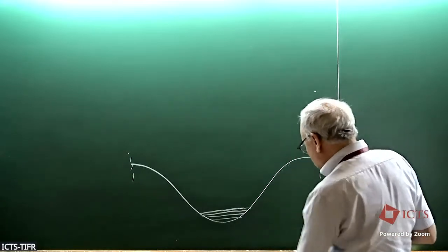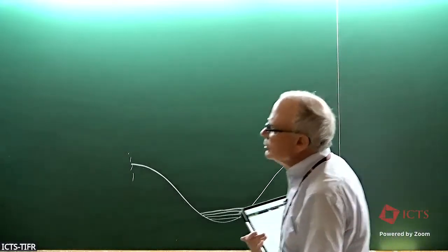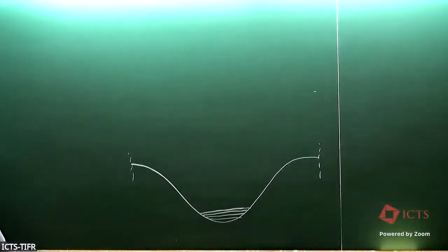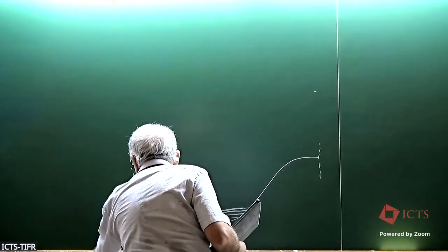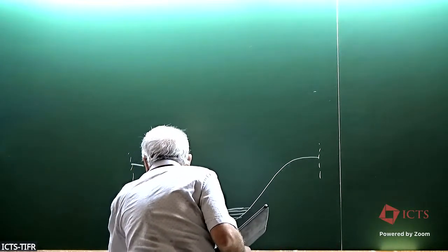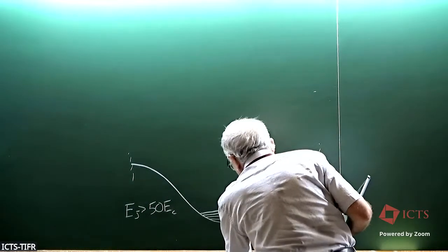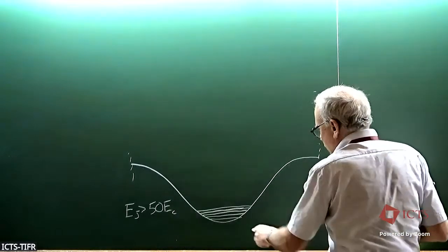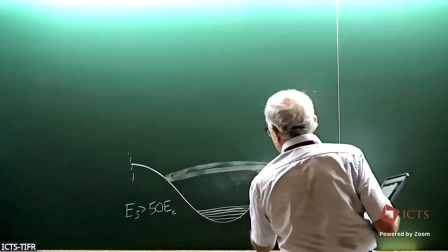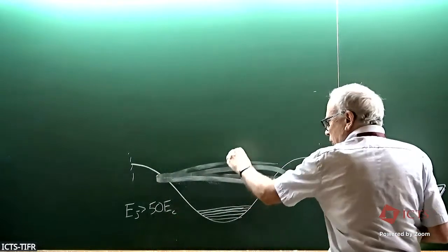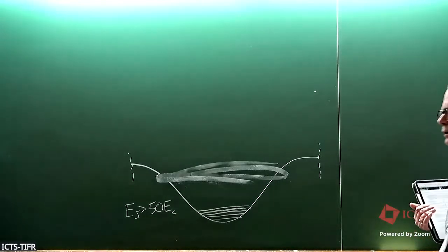I realize that by sketching it this way, I'm in a parameter region where EJ is bigger than 50 EC, because I'm about to draw something where you have really even more energy levels. But this is very slightly anharmonic, and then there's a region where it's a little hard to describe. Yes, there are discrete energy levels, but there's no simple formula for them in this region.